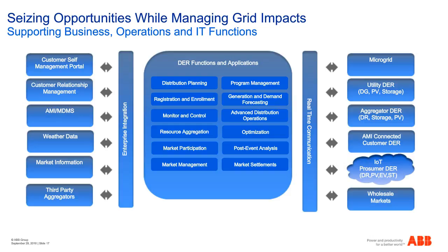We've got aggregated DER, which is dispatched from aggregators, but based on either top-level or aggregate requests from the market or network operator. You could see the utility AMI infrastructure may offer a communication network with DER, or prosumer DER can be accessed via the internet and prosumer's home Wi-Fi, either for communication with smart inverters or home or building management systems.